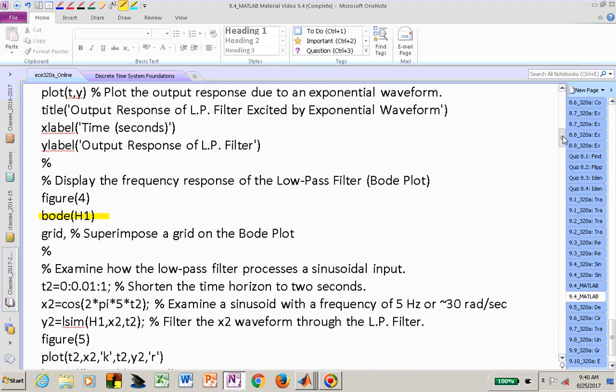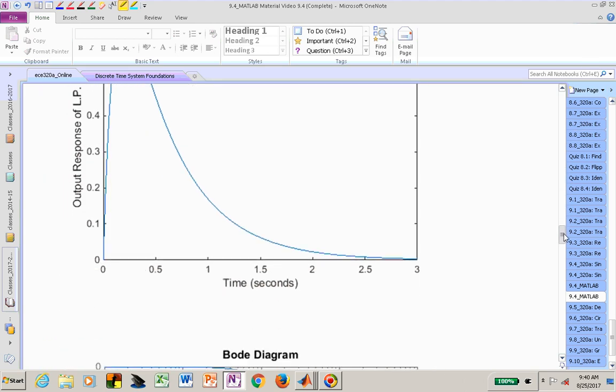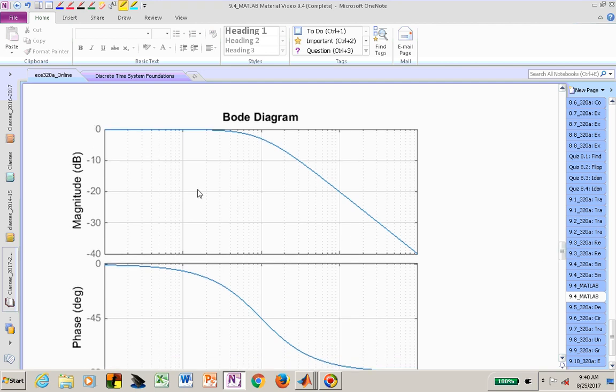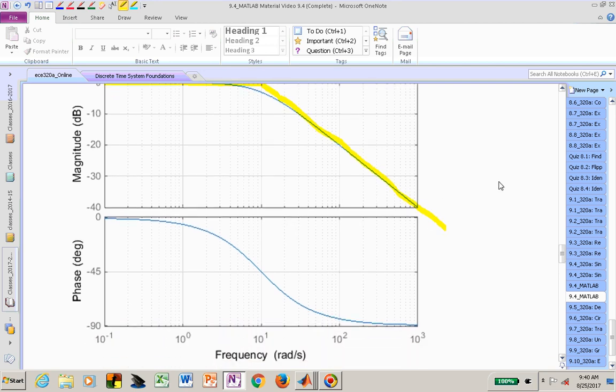And in fact, I've already copied in some of those figure windows. Here's now our Bode plot. We will learn how to do a straight line approximation. We'll go out to 10 and then we'll come down 20 dBs per decade because it's a single pole system. And that would just keep going and going. That's our magnitude response.